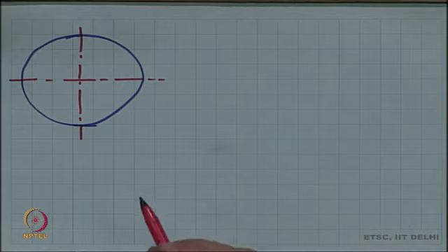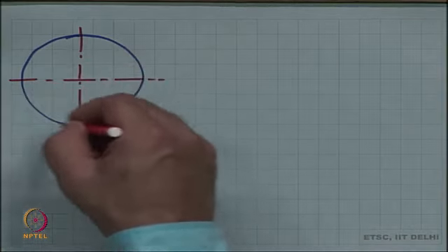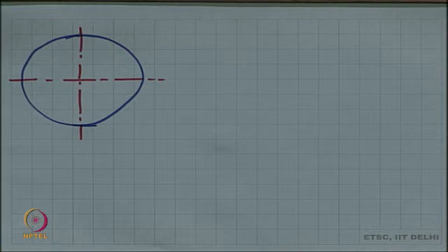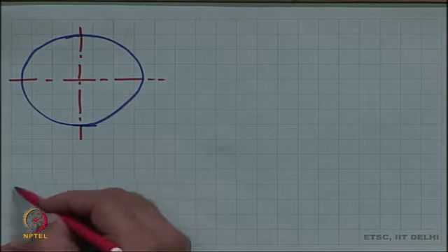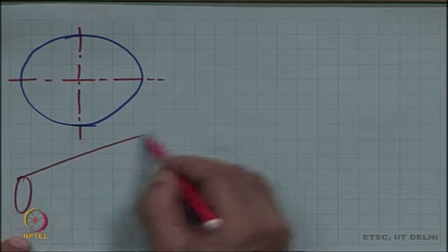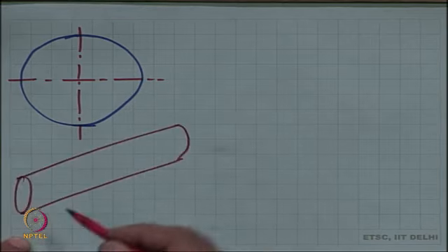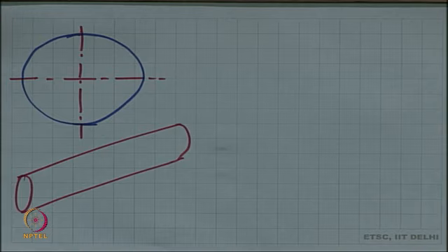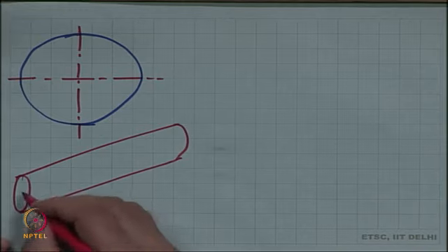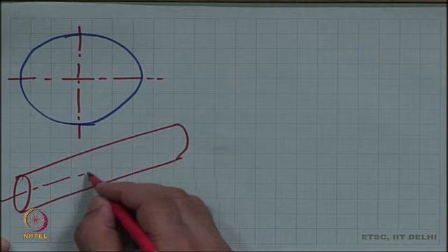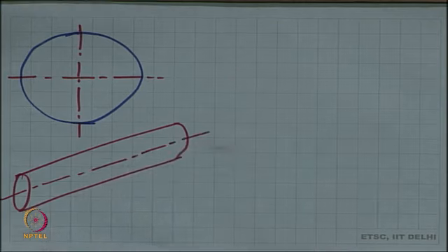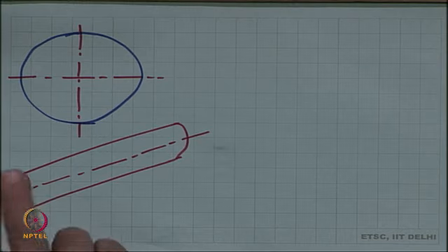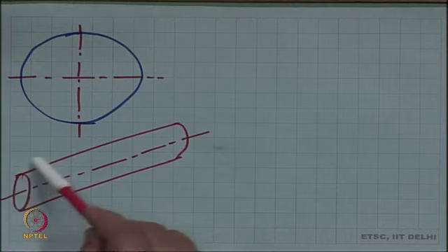And this tells us clearly that this thing is a circular feature. If it was a pipe, the axis of the pipe is the axis of symmetry, and we would then draw this as this symmetry. It tells you that about this axis, the shape is the same everywhere.